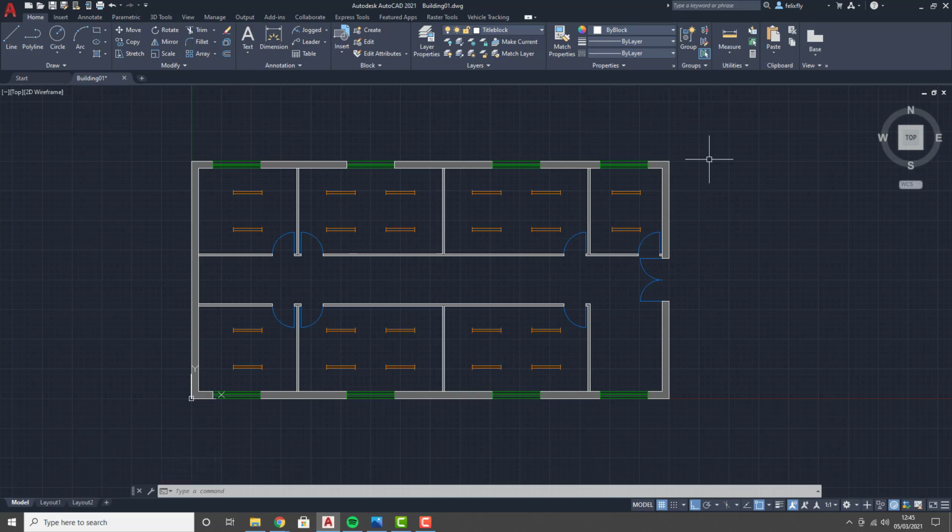Now, if you were to print that actual size, you would need a very big printer to print something 20 meters wide. So you would put that on a sheet of paper, whether it's an A4 sheet, A3, whatever size paper you're going to print on, you would have to show it to scale. And we'll look at scales, but the concept is you would show it smaller than actual size. However, it's drawn to actual size. You don't want to start drawing things to the size that you're going to print it. If you were going to print this out on a piece of paper so that it was only 10 centimeters wide on the sheet of paper, you don't want to be having to do that calculation.